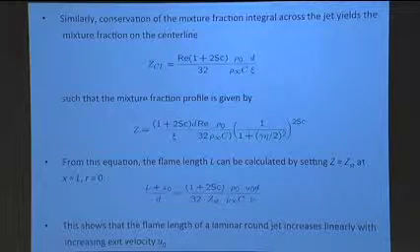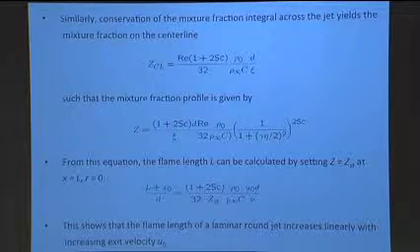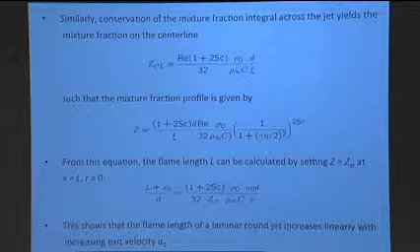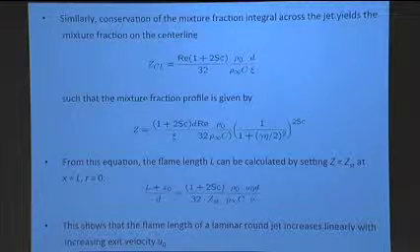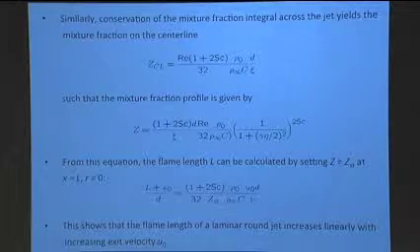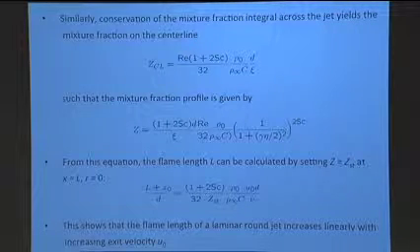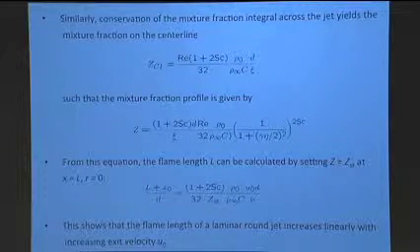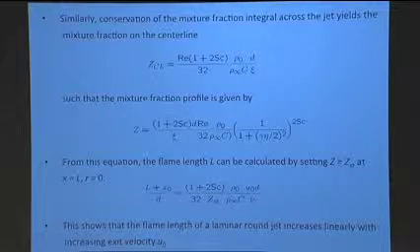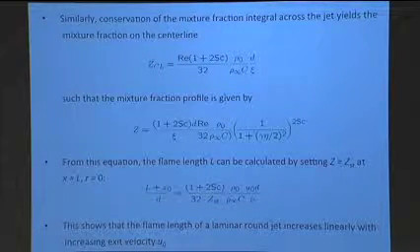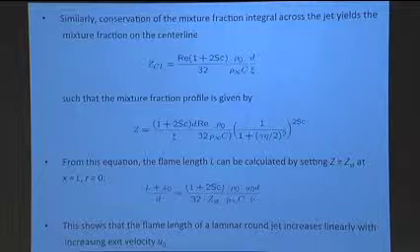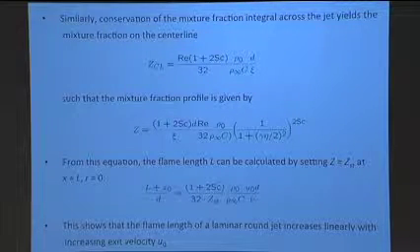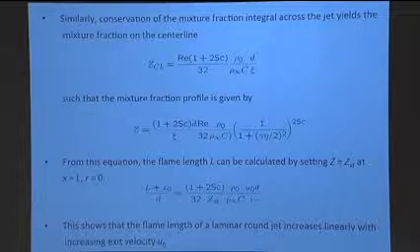And again, we're skipping all the little details, and if you are interested in these, look back at these. The main point I want to point out here, of course, is that the flame length is related to Z stoichiometric. Not lift-off length, the flame height. The smaller Z stoichiometric is, of course, the longer the flame height, which explains some trends you observe when you, for example, dilute the fuel, because if you dilute the fuel, then the stoichiometric mixture fraction moves around in this space, or if you have EGR and the stoichiometric mixture fraction moves around in this space, and that then gives you changes here.